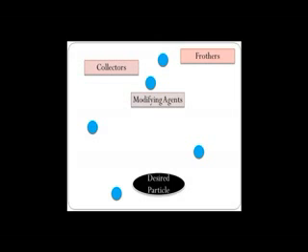As the name implies, the modifying agents modify or alter the properties of both the solution and the particulates present. Modifying agents can render a solution acidic or alkaline depending on what is desired or favorable. It is very important in altering the surface characteristic of the desired so that the collectors may be selective to it alone. Selectivity is important to maximize recovery and minimize the presence of the undesired.